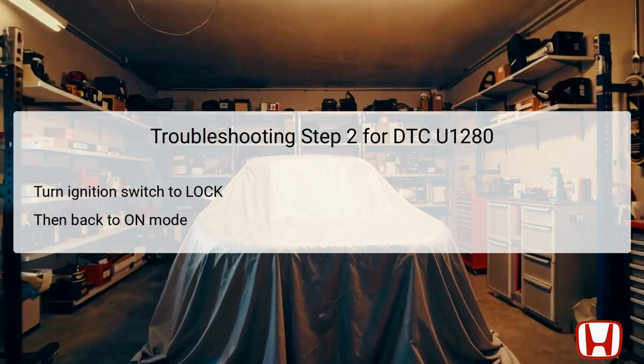By cycling the ignition, any temporary glitches in the electronics may be resolved, allowing you to assess the system's current state more accurately. Ensuring that the vehicle's ignition is properly cycled can help eliminate minor electronic faults that may not warrant deeper investigation. Following the ignition cycling, it's important to wait for at least 6 seconds.